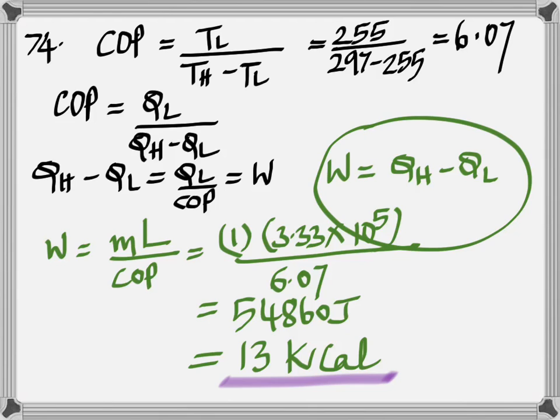Okay, so change in entropy is always dQ by T. And dQ could either be positive or negative. Like if heat enters a system, it's positive, so the entropy will go up. If heat leaves a system, entropy goes down. So you have to remember that. You have to have that picture in your head. So, is this losing heat? Its entropy is going down. Change is negative. If it's gaining heat, it's positive.